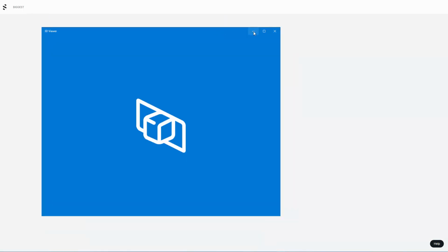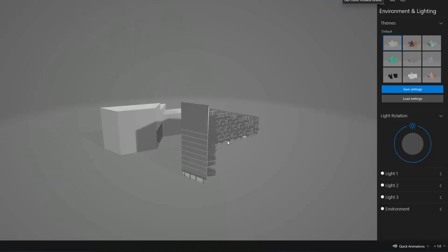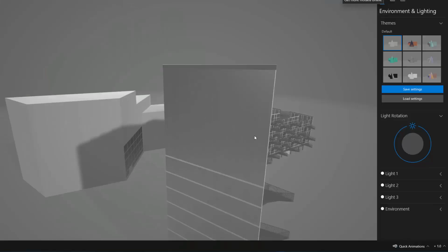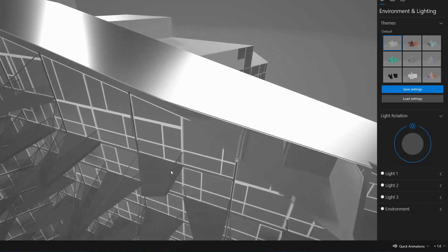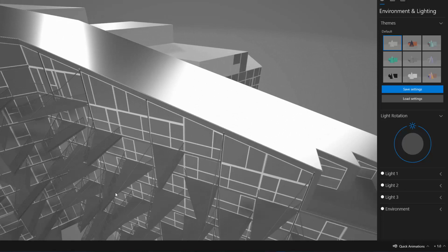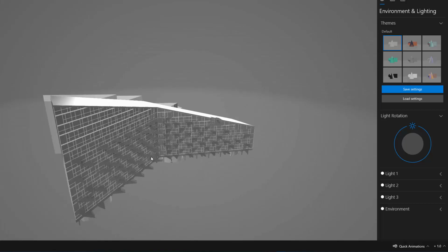It's taking a bit of time to load up. So again, it was a very big, here it is. This was the one that was 155 megs, and I reduced it down to 6, so you can see what was causing the headaches there with all the meshing on the balcony. So again, before you bring the data in, reduce that polygon count.